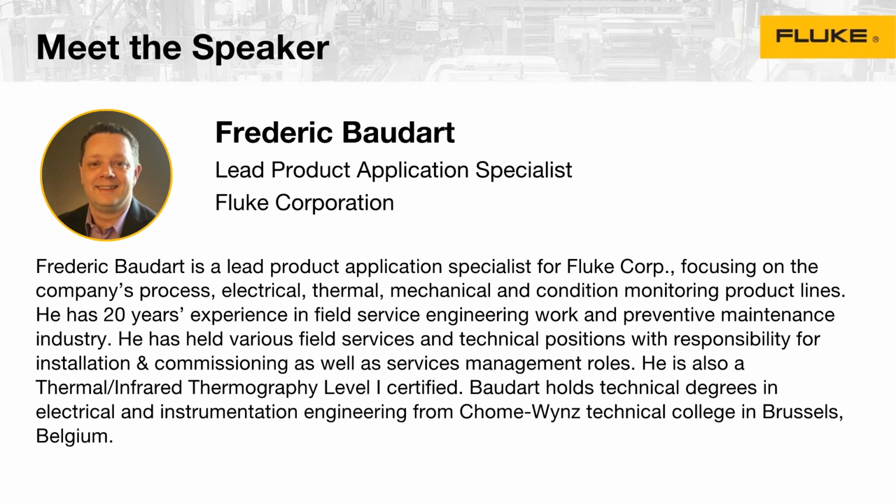Sure. So first of all, good morning. The reason why I wanted to present this topic is really twofold. We have a lot of customers who are starting to dabble and get involved with preventive and proactive maintenance, and a lot of them either have used or would like to use some type of measurement, and often they start with either vibration or a thermal imager. I think it's getting more and more common to use a thermal imager because it's a great tool to find anomaly issues, and it really is a picture's worth 1,000 words.